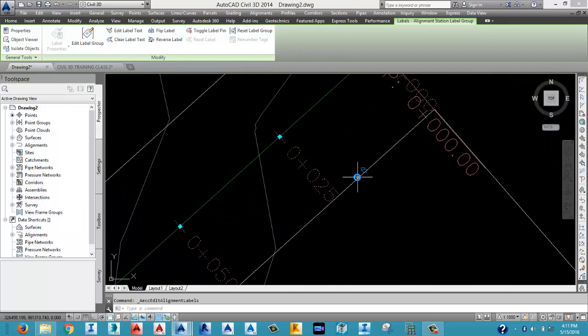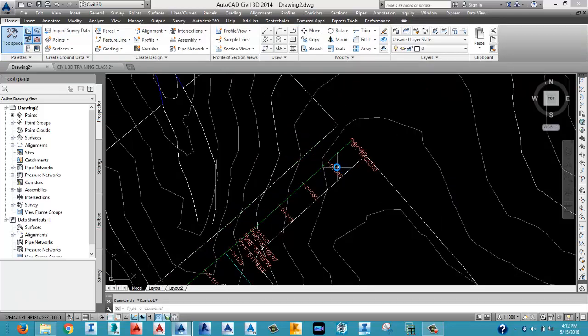How do you change it? Just click on this tag here. Click on the tag, then click on the drop down. See, perpendicular with tick. OK. What does it mean? You see the effect. Click apply and OK, and you see the change. Initially when it was parallel, your label was parallel along with your alignment line. But now it's perpendicular to your alignment line. So that's how those things work.